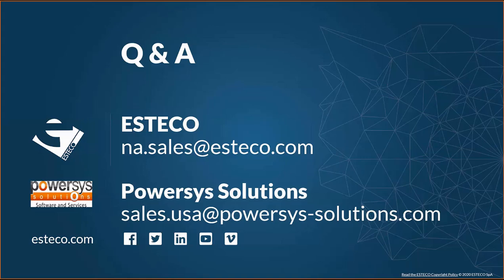So that gets onto the modeFRONTIER side. Is that an input value that can be assigned? From the point of view of modeFRONTIER, variables can be either continuous or discrete, and modeFRONTIER can handle integer variables as long as they are defined in the model, and the model can take those inputs within a well-defined integer range. modeFRONTIER can control them, and there are specific algorithms and strategies to do DOE and optimization using such variables. So yes, it is possible.